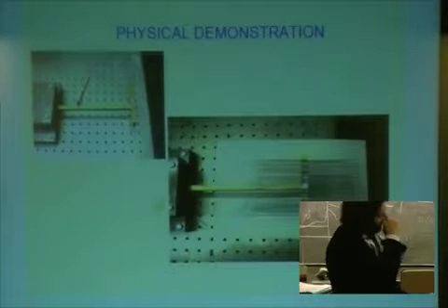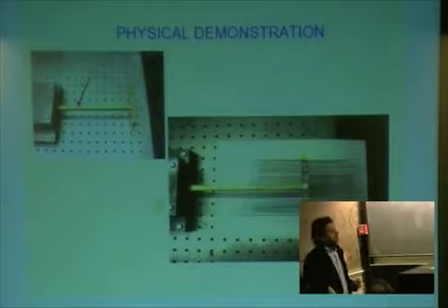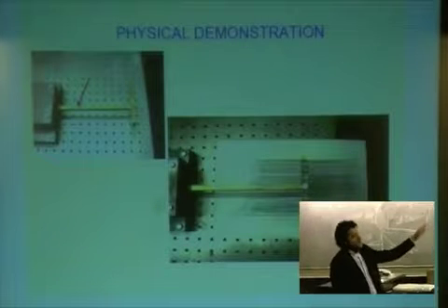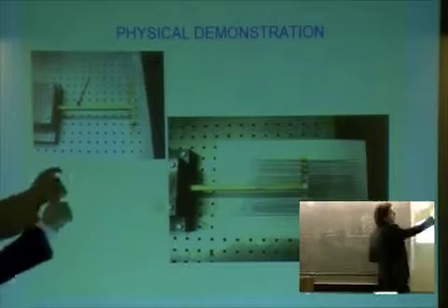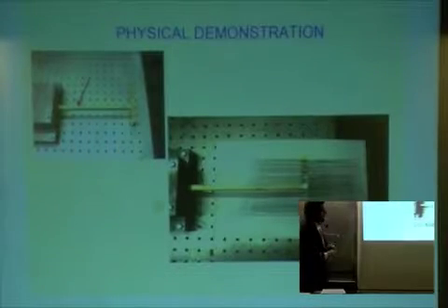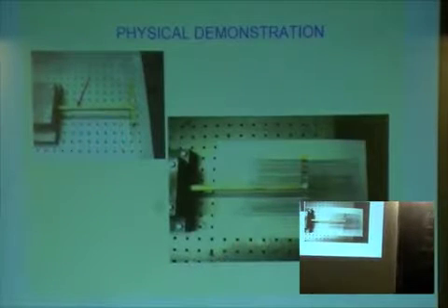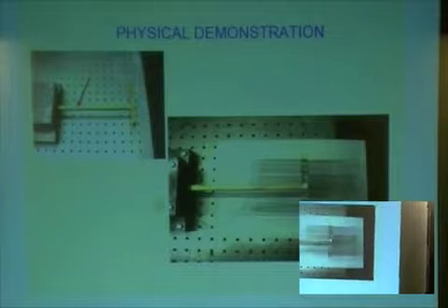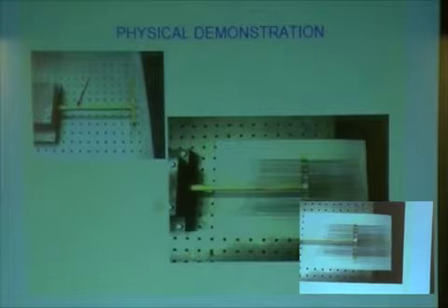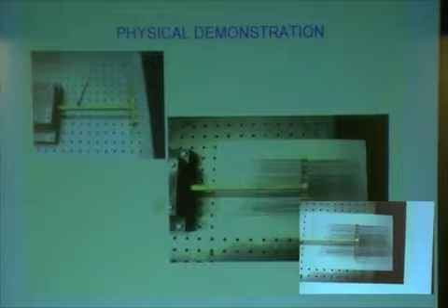We also have some physical experiments that we made in order to test this kind of phenomena. In this case you have a T-beam. This is the main structure, the master structure. It's a continuous structure. Then you can put over there a set of resonators. There are 100 resonators, which are beams. And you select the frequency distributions of them, meaning the length of them, in order to fit the frequency distribution that we found. So the probability density, the best probability density function.